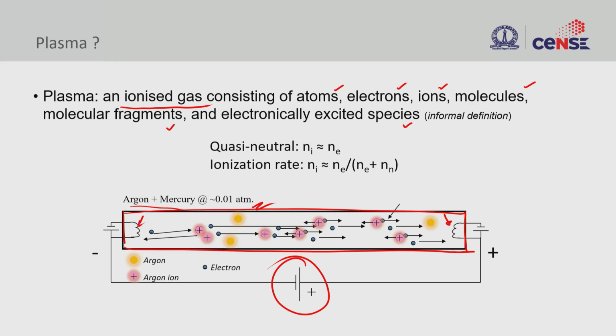The first electron will be generated from the electrode itself, but it cannot travel the whole distance. So whatever gases we have should supply additional electrons. Those additional electrons will be accelerated, which is the reason we need a large voltage, to the other end, and during their accelerated propagation, they will collide and generate more electrons and so on.